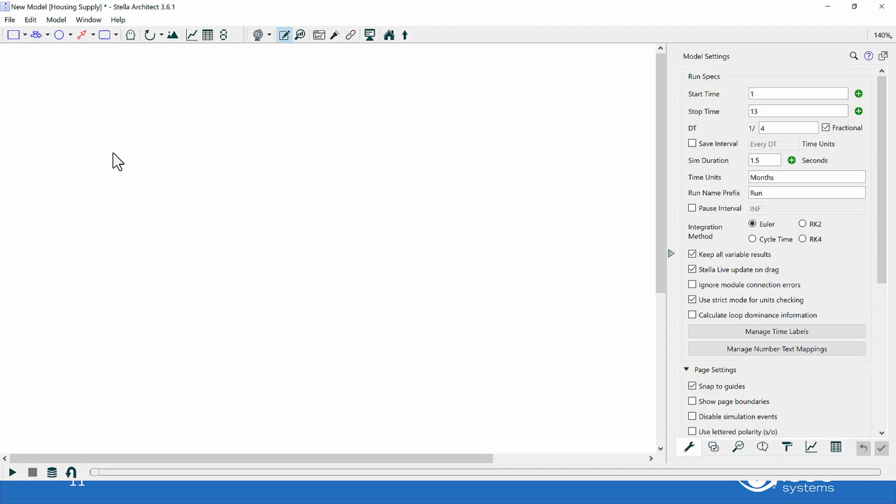We know that. When I'm in here, how do I know I'm in a module? This is an important question. Well, first of all, at the top, we have the name of the module next to the file name in square brackets. Secondly, these things appear on the side of the tool palette. The one on the right takes us up one level.